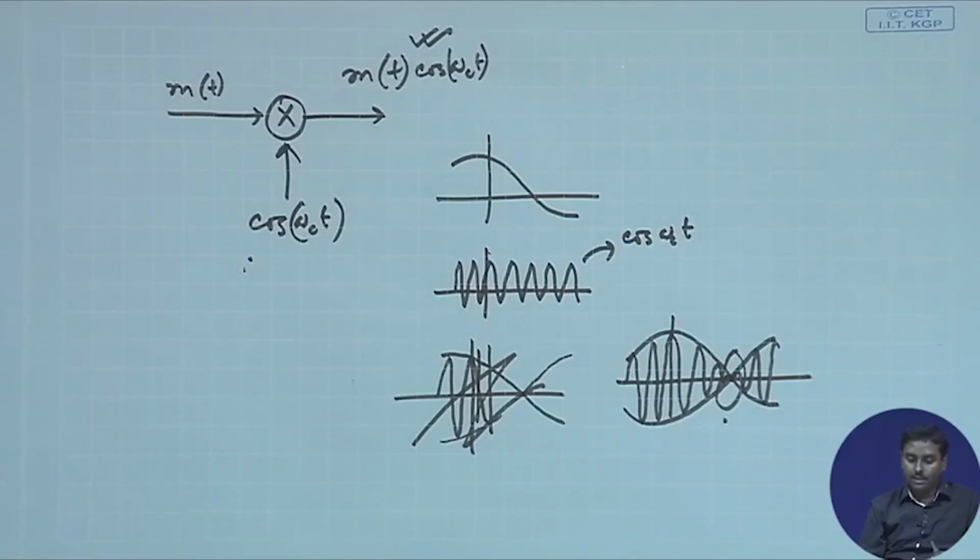Okay. So, in the last class, we were trying to show that if we do the simplest form of modulation, which we are calling DSB SC, that DSB part is clear, probably SC is still not clear, that will be clear after some discussion. But that particular modulation, which is the simplest of amplitude modulation, where we just multiply a signal m(t) with cos omega_c t, we have shown the frequency domain response of that.